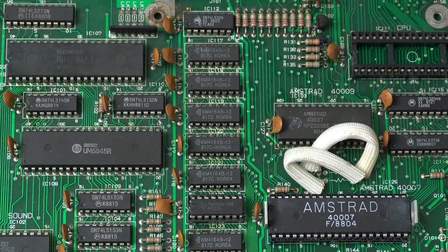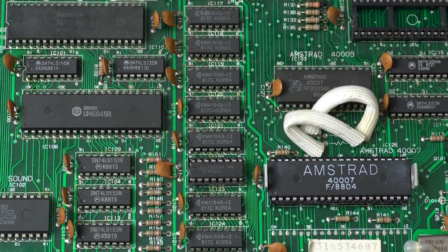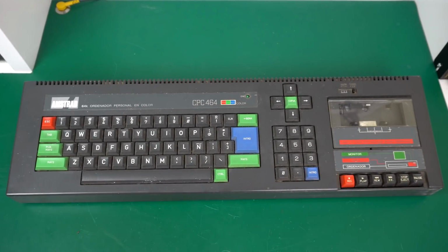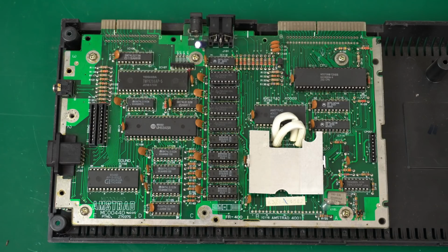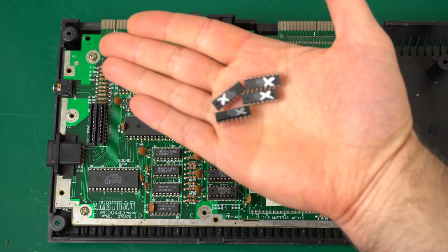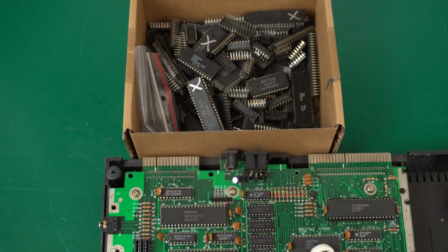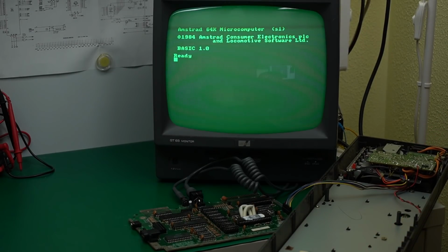I really wanted to see what effects other missing ICs had on the display. I didn't have any other boards with socketed RAM chips, but in the interest of science, I desoldered all the RAM ICs on this board I had in my repair pile and socketed them all. If it makes you feel any better, 4 of those RAM ICs were faulty, so I kinda needed to do this anyway. So let's see, starting from the top, what kind of effects each missing chip has.